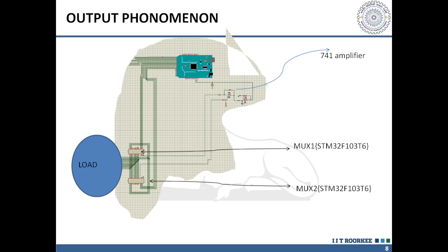Once we have measured all the voltages, we repeat this process by putting the current source between the second and third electrode, and then we measure the data with the remaining outputs. This process repeats again: we put a current source between the third and fourth electrode, and we get all the difference voltages from all the electrodes.